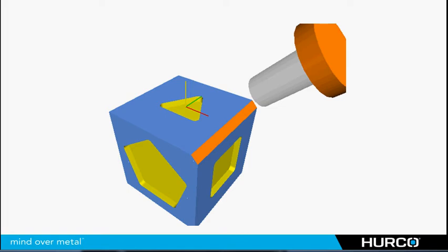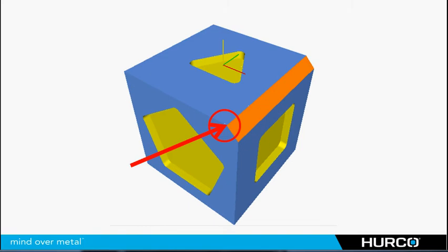We're going to orient to something that makes sense for this. In this particular case, I'm not going to take an origin point to a corner. I'm going to go to the edge of the feature that I'm machining. So in this case, I want to do a 1/2-inch chamfer on the edge of the part. I'm going to stop a 1/2 inch shy of the edge of the block.